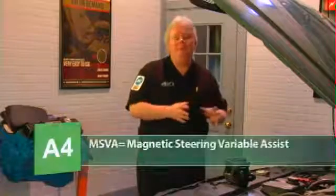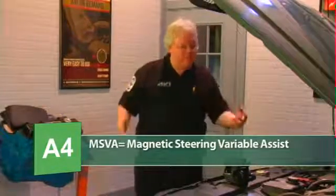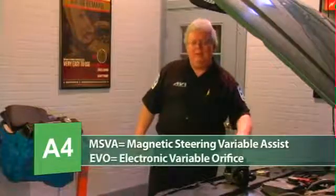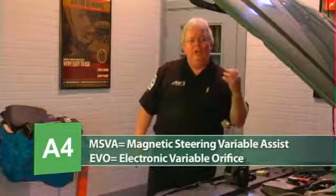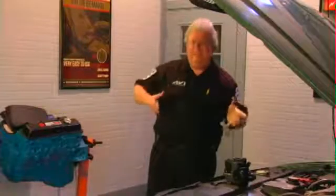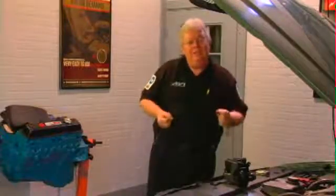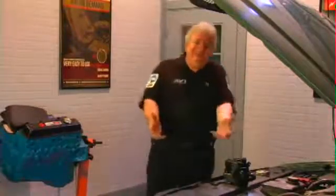Those are called MSVA, magnetic steering variable assist. They work on the same principle as the EVO, electronic variable orifice. They simply look for vehicle speed, and as the vehicle speed goes down, we assist. We allow more power steering assist for the parking lot maneuvers where you need it, but as the vehicle speeds up, we take that assistance away.